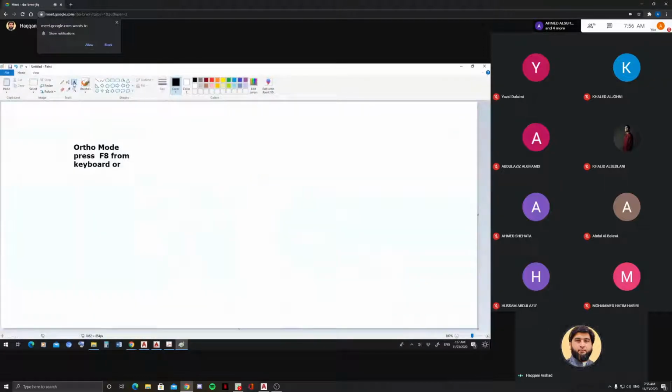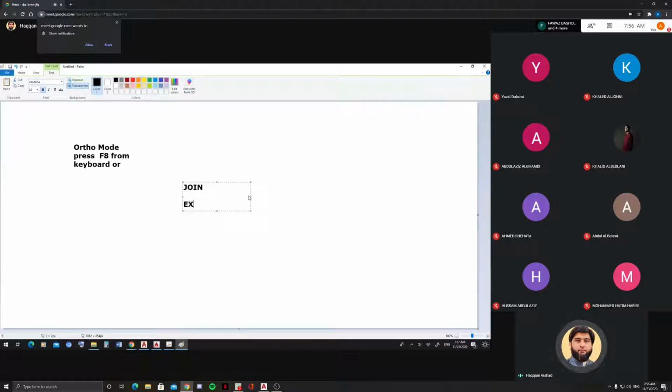So what we have seen today, we have seen the same thing. Join. We need to join. We need to extrude it. Okay. And if you want to subtract something, first you need to make the shape, whatever shape, like a circle or a hole or whatever slot. Okay. Then extrude and subtract.